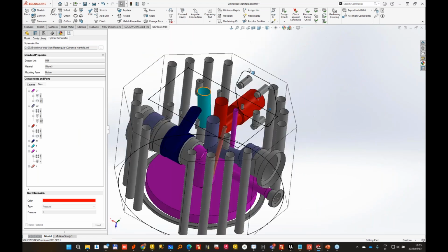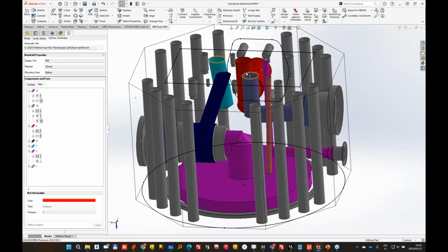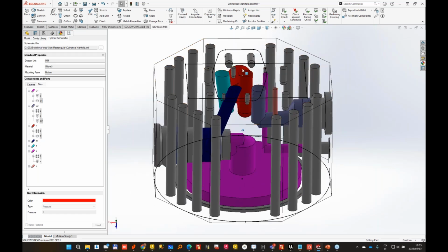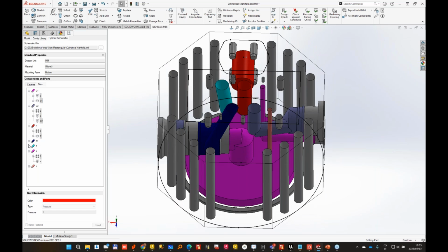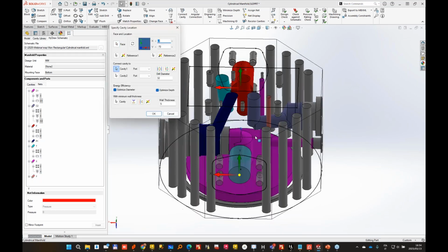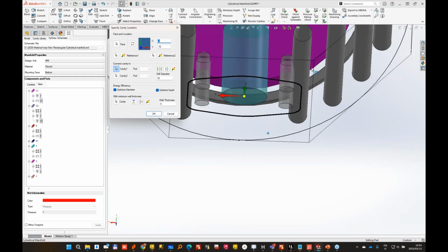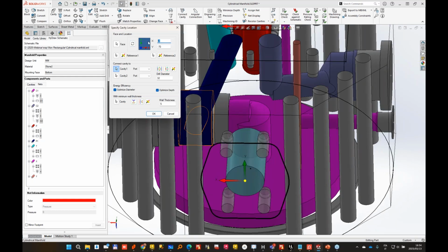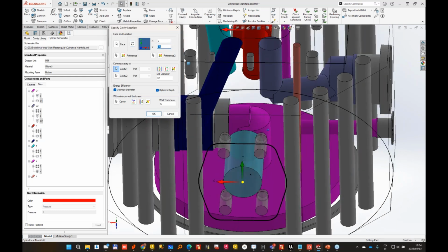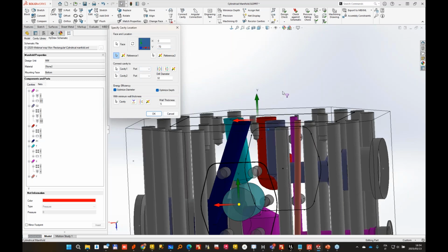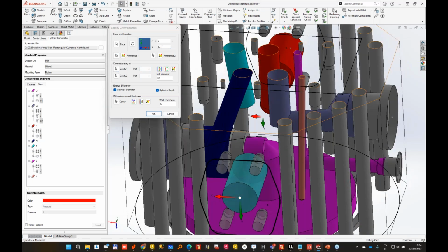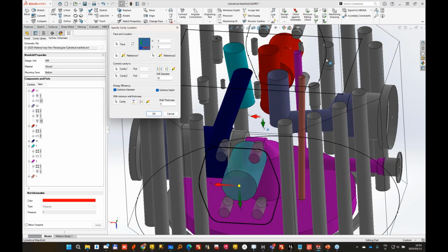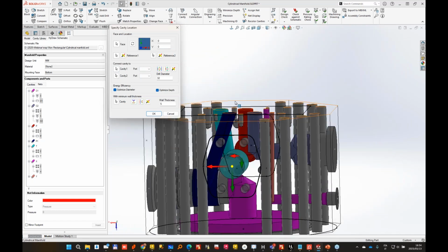I need the tank port. So I use the opposite of the P face. So I'll take my tank and insert here. Again, since this is interfering with the bolt holes, I will rotate the flange. I will put it at 0. And I can reference with respect to the other cavity, maybe at 0. So in this case, they are aligned on the opposite face.